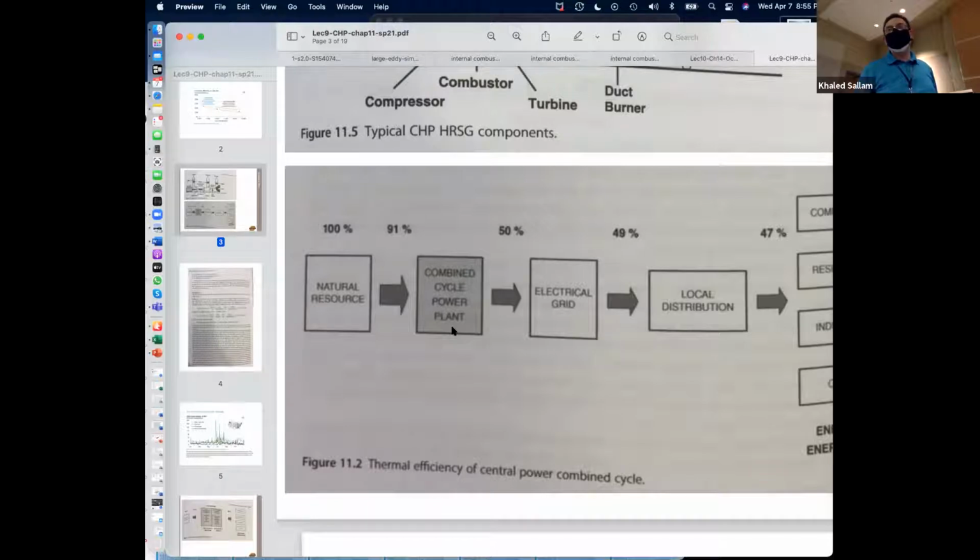Because, I mean, you're just making a flame, and as long as you spend enough time between the flame and the water, the water will get the heat. But if the flame leaves very quickly or the hot exhaust leaves very quickly and you don't have enough coil, there's not enough pipe, you may end up losing the energy to the exhaust. Okay? But anyway, check on the efficiency of the furnace that you're going to choose.